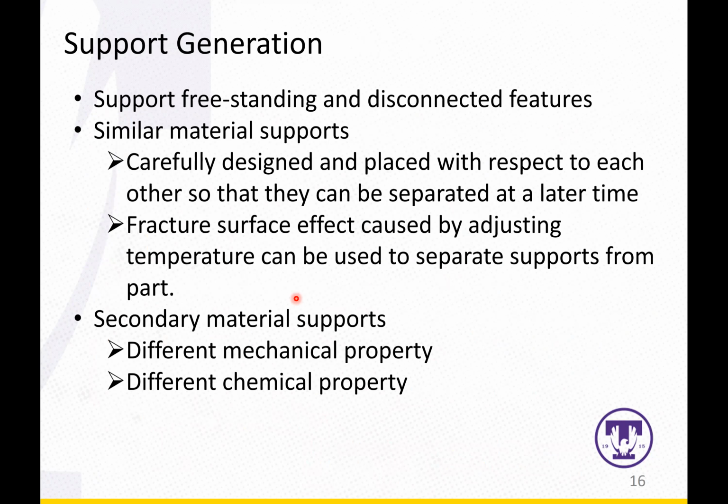So that's undesired. Also, the fracture surface effect caused by adjusting temperature can be used to separate support from the part. But that really depends on how different the material you use for support is versus the printing material.